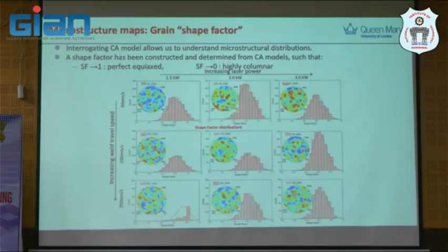It's not just looking at it in 2D, but we are now looking at it in 3D and seeing the morphology in 3D, and then we calculate the shape factor, which means if it's smaller, it will be closer to circular. If it's larger, it's elongated, something like that. That's what it means. Or another way around, I'm sorry. Circularity is 1, sorry. Yeah, that means it's actually intermediate here. Sorry, my bad. And then the shape factor we construct, if you see here, equiaxed are closer to circularity 1, shape factor closer to 1. If closer to 0, it's more elongated.